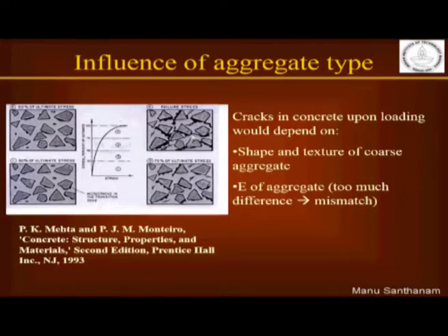Okay, so if you have tested high strength concrete in your lab, or if you are going to be testing high strength concrete in your lab very soon, just take a look at what the fracture surface looks like after the test is completed. You will see that the failure for the high strength concrete is explosive. That means you have chunks falling off, and you will often see that the crack has gone right through the aggregate. Okay, so very important distinction.